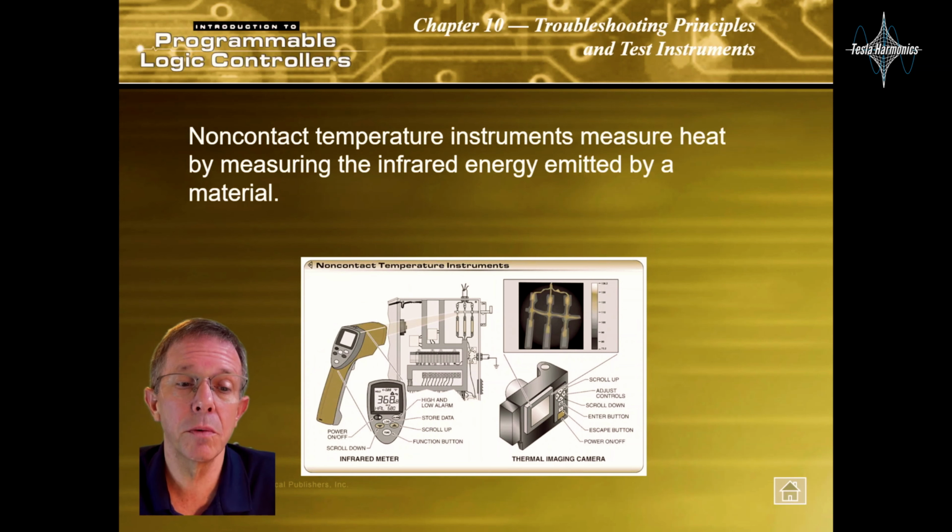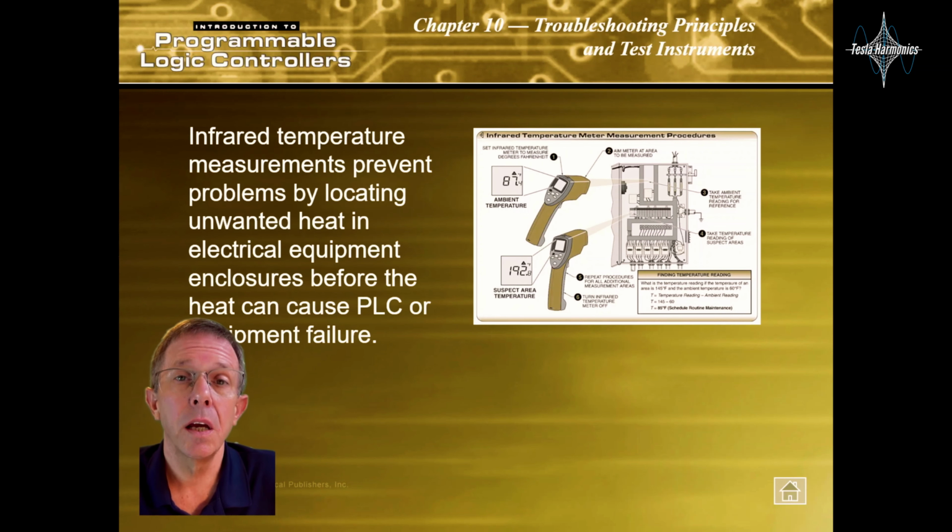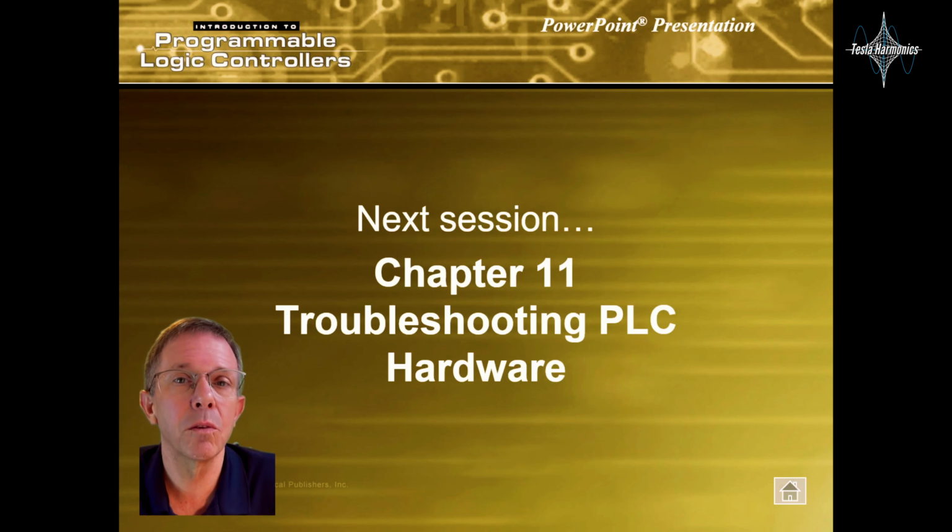Non-contact temperature instruments measure heat by measuring the infrared energy emitted by a material. Infrared temperature measurements prevent problems by locating unwanted heat in electrical equipment enclosures before the heat can cause PLC or equipment failures.